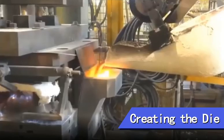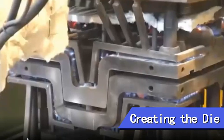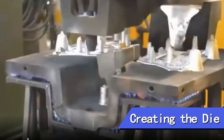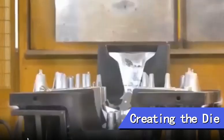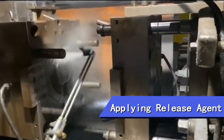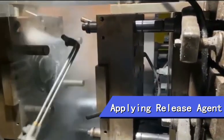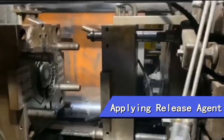A die is created with hardened tool steel in the shape of the desired parts. The die may contain multiple cavities for producing multiple parts simultaneously. Applying release agent. A release agent is applied to the die to prevent the molten metal from sticking to the steel during the casting process.